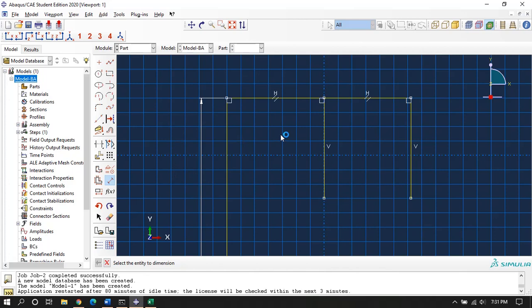One thing that we have to keep in mind over here is that the units must be consistent throughout the modeling process. I am considering FPS system in which kips and inches will be used throughout the modeling for the forces and lengths dimensions. You can also use metric system, but the main consideration that must be kept in mind is that the units must be consistent throughout. 144. The bay width I am considering is also 12 feet, which is 144 inches.